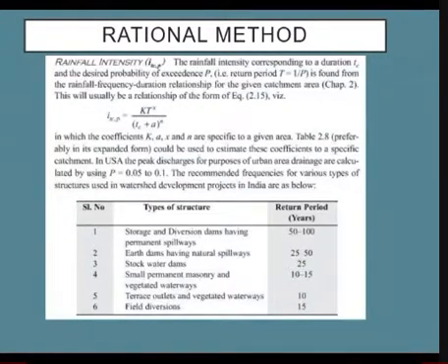2. Earth dams having natural spillways, 25 to 50 years. 3. Stock water dams, 25 years. 4. Small permanent masonry and vegetated waterways, 10 to 15 years. 5. Terrace outlets and vegetated waterways, 10 years. 6. Field diversions, 15 years.